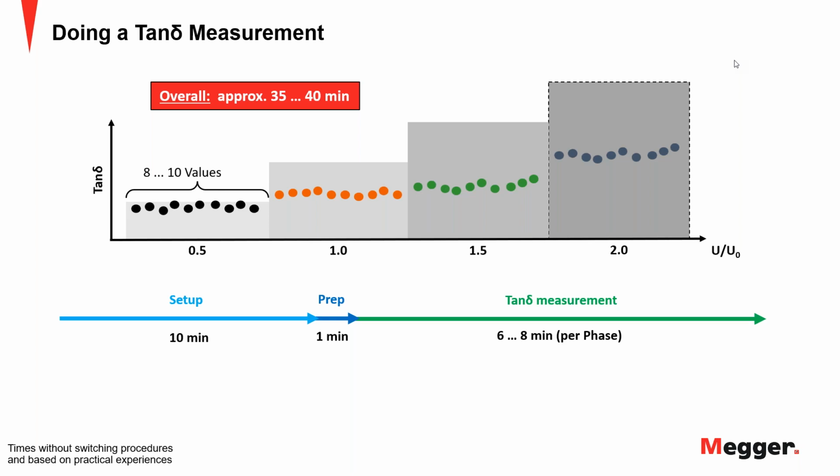With service-aged cables, in addition to those two types of defects, we also try to determine any effects from aging of the cable. And that's why you have different methods to address these different types of defects.